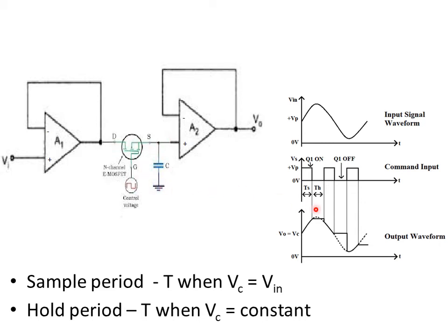So during this time when VC is 0, whatever value was in the capacitor, charged to the instantaneous value of the input, it will retain the value found just at that instant previous to VC being turned 0. It will retain this value until VC is turned on high again.